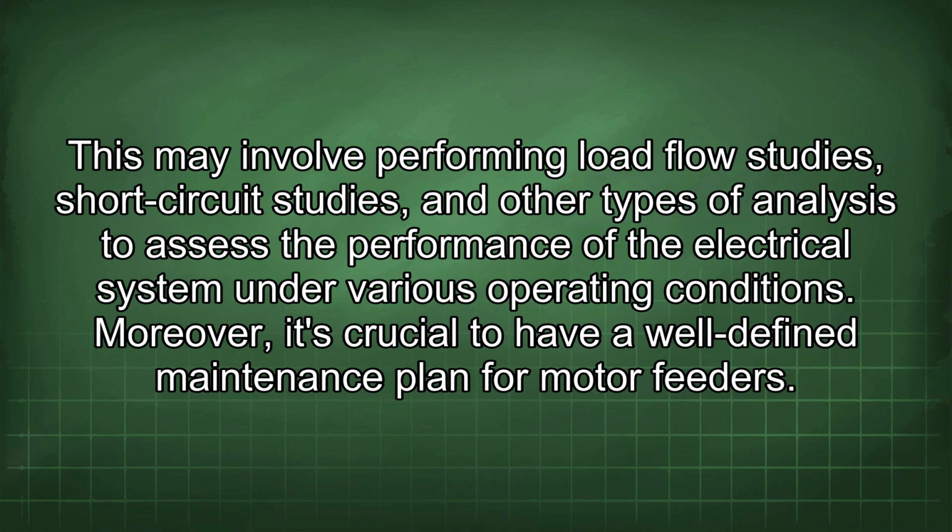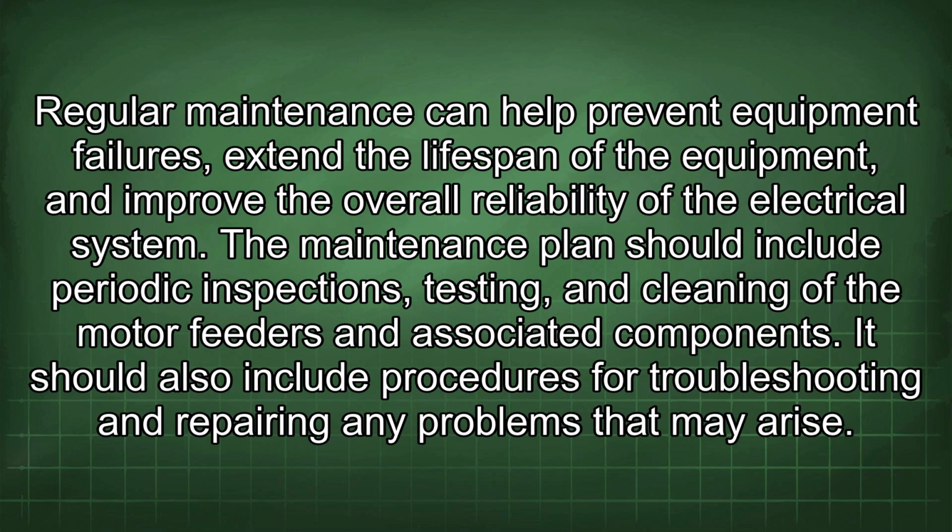Moreover, it's crucial to have a well-defined maintenance plan for motor feeders. Regular maintenance can help prevent equipment failures, extend the lifespan of the equipment, and improve the overall reliability of the electrical system. The maintenance plan should include periodic inspections, testing, and cleaning of the motor feeders and associated components. It should also include procedures for troubleshooting and repairing any problems that may arise.